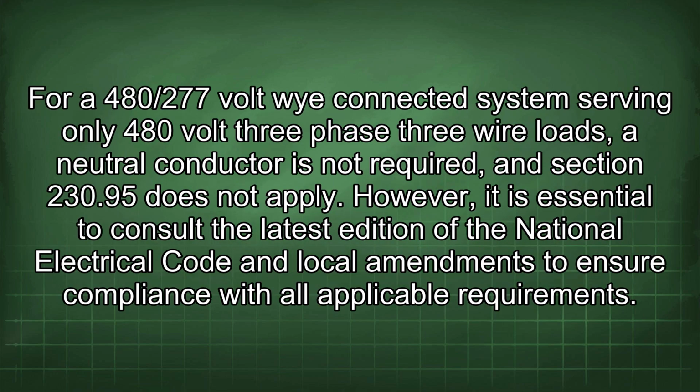For a 480/277-volt Y-connected system serving only 480-volt three-phase 3-wire loads, a neutral conductor is not required, and Section 230.95 does not apply. However, it is essential to consult the latest edition of the National Electrical Code and local amendments to ensure compliance with all applicable requirements.